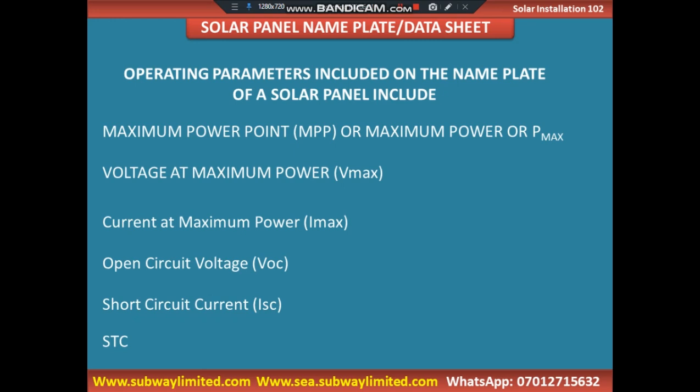We talked about 1000 watts per square meter illumination, then we talked about 25 degrees Celsius cell temperature, and we talked about 1.5 atmospheric spectral condition. So when you look at any solar panel nameplate, you are bound to see these figures.